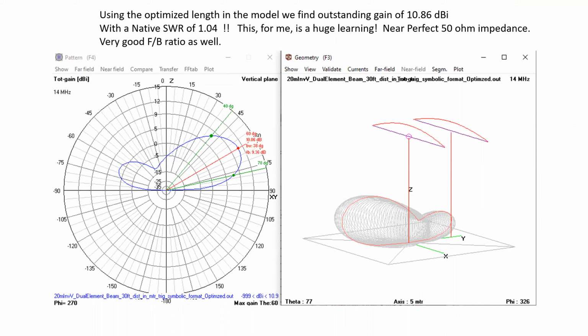I'm pretty sure. Could be wrong. I have a comment on that, Mike. This is Jack W2STM. Bob, unless I'm incorrect, the ARRL has long required that gain values given for antennas be referenced to a dipole. Oh, that's it. So there's at least a 2.15 dB difference in gain between isotropic and, well, a dipole has 2.15 dB of gain over isotropic to start with.